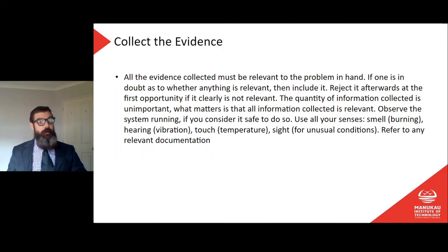The opposite is true as well. If there's one power point faulty in a room, they're saying, oh, there's no power out of it every time I plug something in, but all the other power points in the room work. Okay, well then I'm probably not looking at the switchboard, because it seems very unlikely that that power point is on its own circuit breaker and that circuit breaker is blown. It seems far more likely that power point will be on the same circuit breaker as other power points, and if there's only one that's off, it's probably not the circuit breaker. So have a look for that point of commonality.